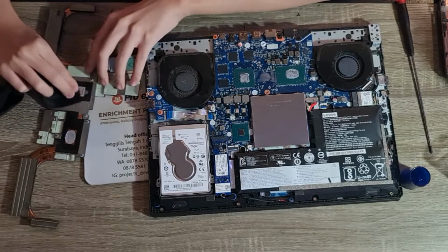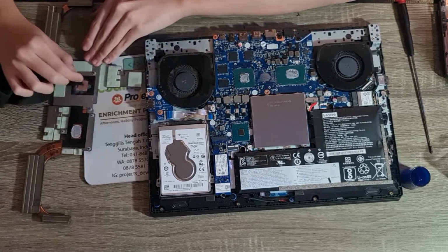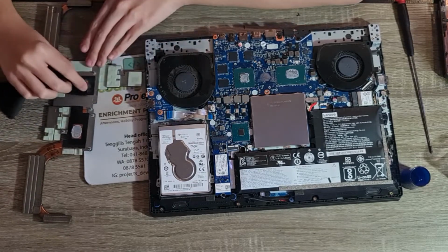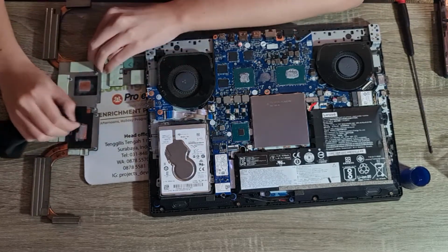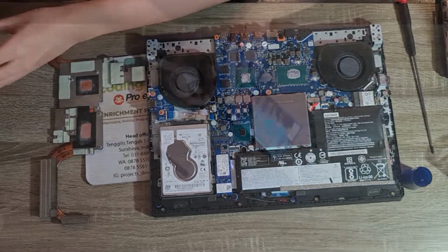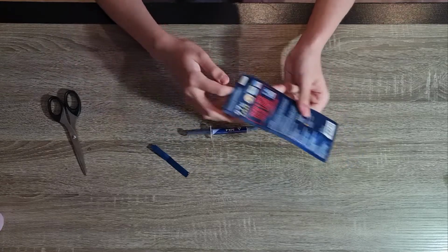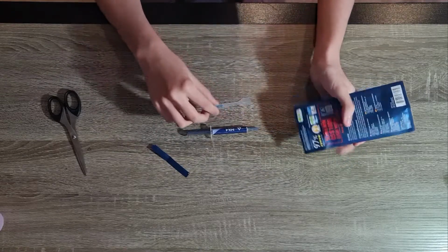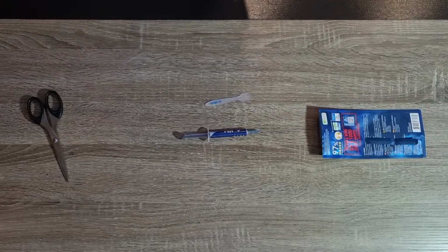Now is also a good time to replace the thermal paste of the CPU and GPU. It is an essential paste that transfers the heat from the CPU to the heatsink by covering microscopic holes. The first step is to remove the excess thermal paste with a wipe and rubbing alcohol. Second, open the thermal paste package and find a syringe with thermal paste inside it. Some companies do provide a thermal paste applier like this, but it isn't really necessary.